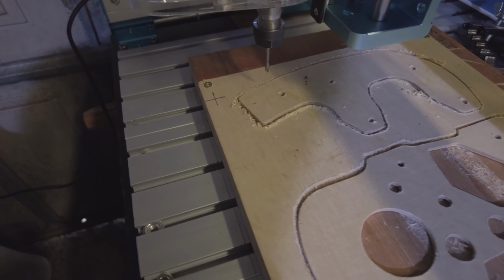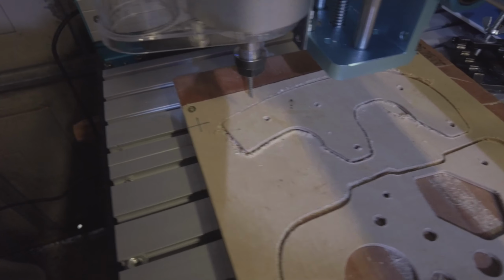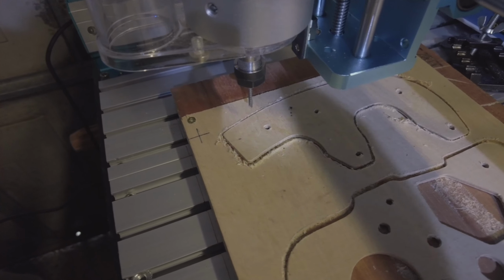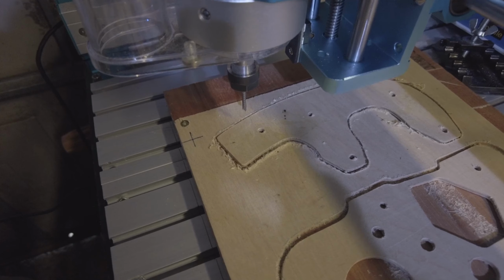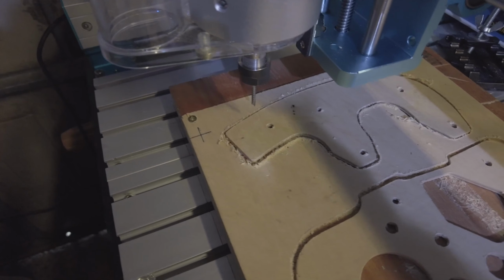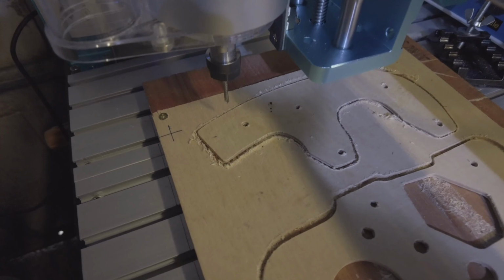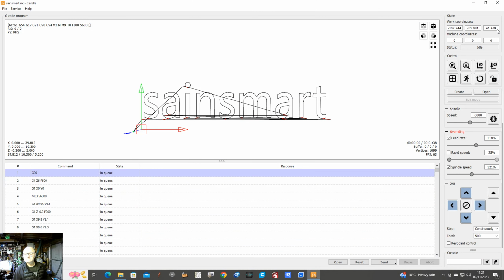Now you would change your cutter, whatever the cutter is that you're putting in for that particular toolpath. You would touch off as normal, and when you touch off, those values on the screen would probably change because you will never get it back to exactly that, but it's touched off. So that will be different in that box there for the Z axis. Then imagine that we've done the cutter change and we're running another toolpath.